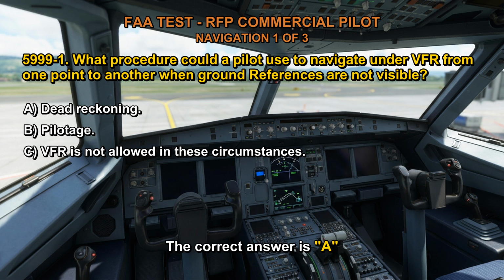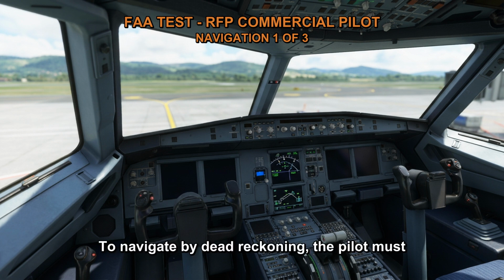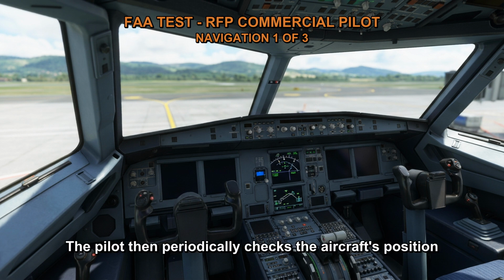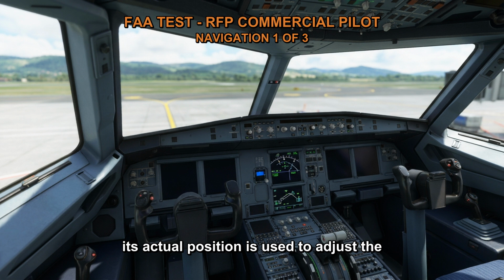The correct answer is A. Dead reckoning is a method of navigation that uses estimates of the aircraft's speed, direction, and time to determine its position. It can be used when ground references are not visible, such as when flying over water or at night. To navigate by dead reckoning, the pilot must first establish a ground track. This is done by setting the aircraft's heading and speed. The pilot then periodically checks the aircraft's position using a navigation instrument, such as a compass or GPS. The difference between the aircraft's estimated position and its actual position is used to adjust the heading and speed.